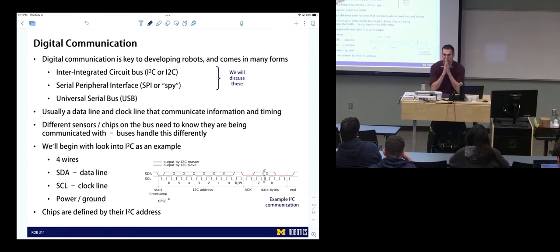What's the purpose of the clock line? It's not a trick question. To make sure the data's coming in live, to sync it. Sync it how? Like when it's sent versus when it's received. Close. How does it know? Does it give a timestamp on the data? Also close. It tells it when the bits are ending and starting. If you're looking at the data line and it was all ones, how would you know how many bits were just transferred? What the clock line does is separate the bits.